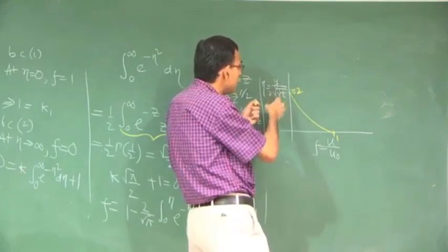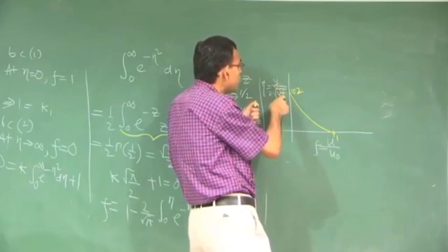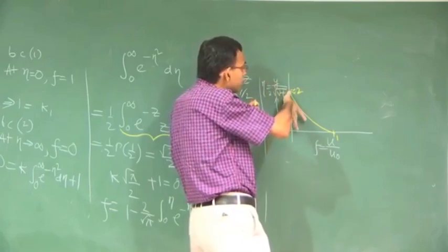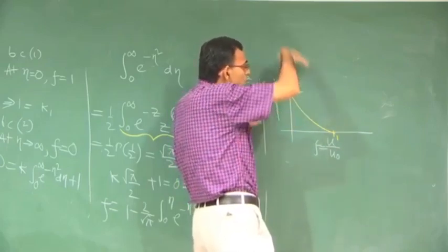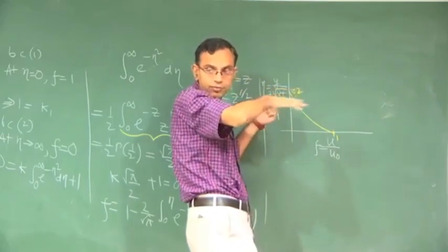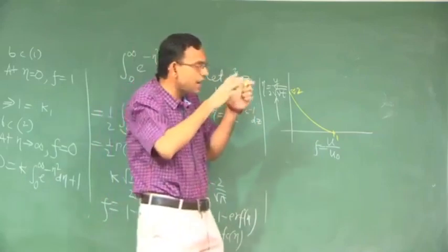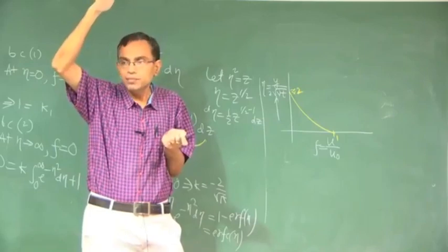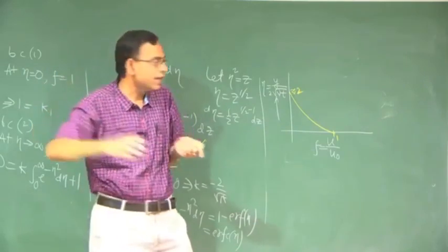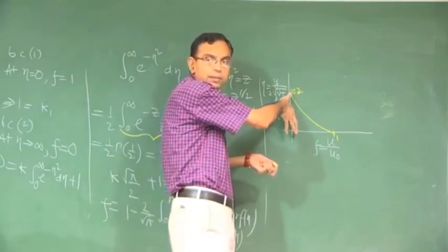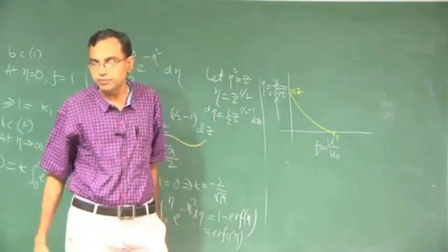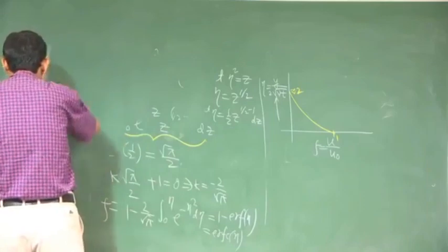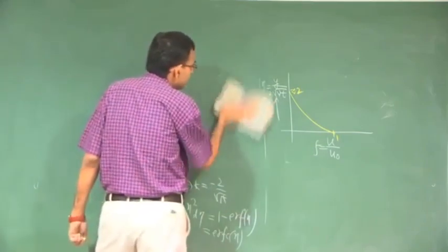So, you can understand that with more time you have more penetration depth y, but beyond eta equal to 2, the outer fluid does not understand the effect of the movement of the plate. So, this gives a nice physical insight to the problem. Although technically at y tends to infinity, any fluid will feel the effect of the plate, but for all practical purposes beyond this non-dimensional thickness, the fluid does not feel the effect of the plate. We will consider the next problem now, which is the Stokes' second problem.